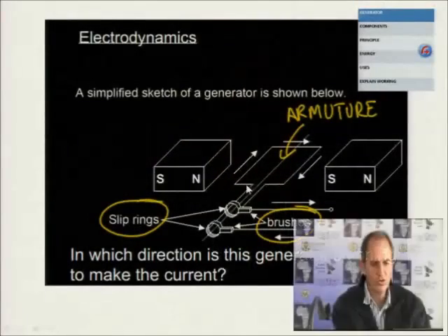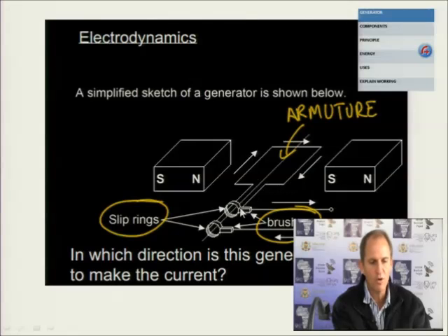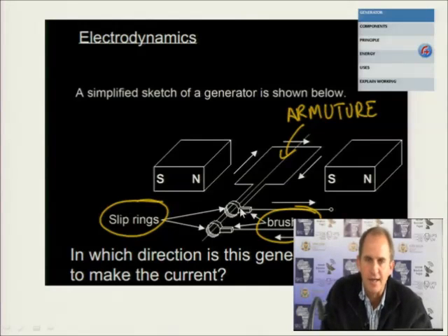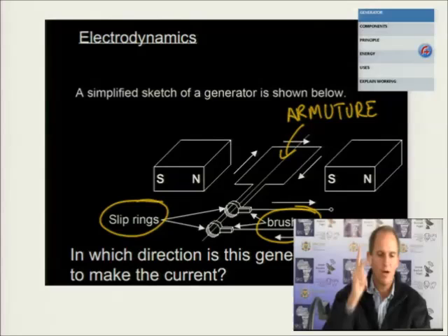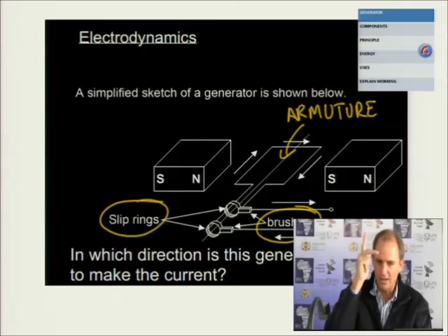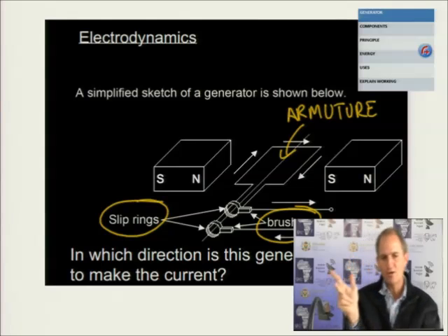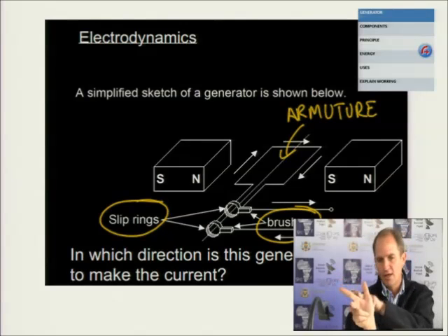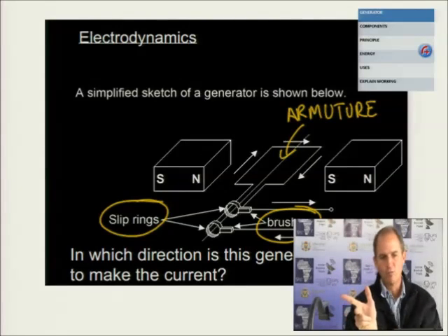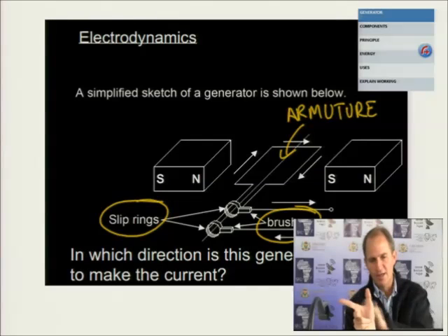Which 2 did I provide here? I provided you with the magnetic field direction, which is from north to south, so it will be from the left to the right. I've provided you with the induced current. So I want to know in what direction I am turning this generator. If I apply my right hand rule, and please guys, take your right hand, I can say, all right, my current direction will be in that direction. It is going from north to south, the index finger.